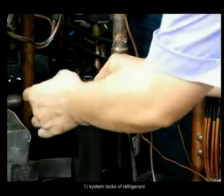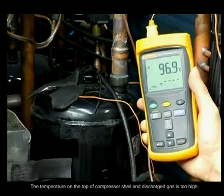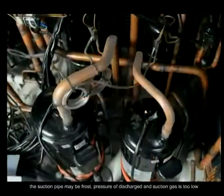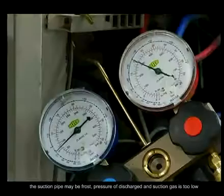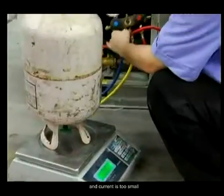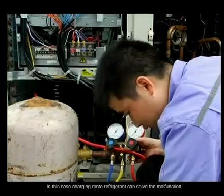One, the system lacks refrigerant. The temperature on the top of the compressor shell and of the discharged gas is too high. The suction pipe may be frosted. Pressure of discharged and suction gas is too low, and current is too small. In this case, charging more refrigerant can solve the malfunction.